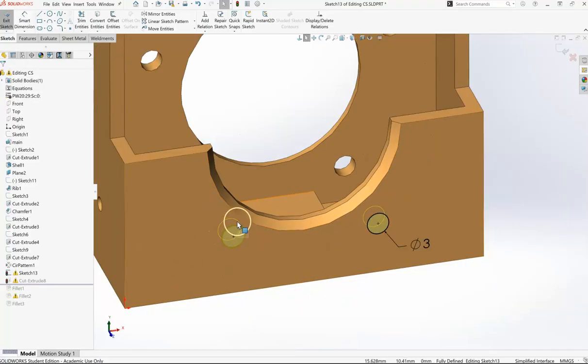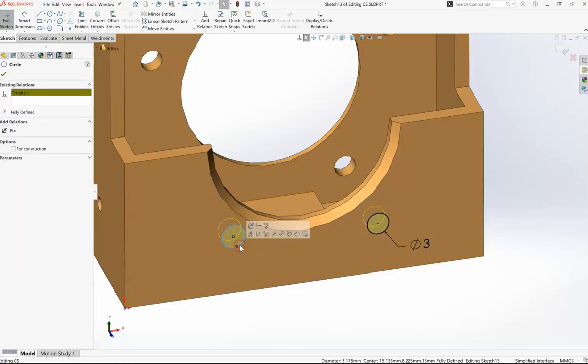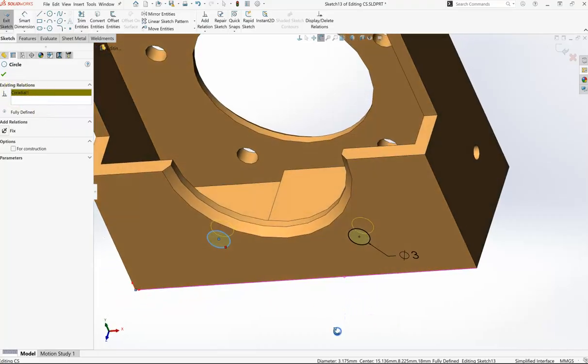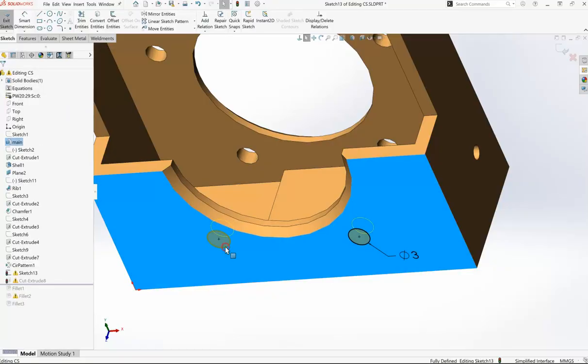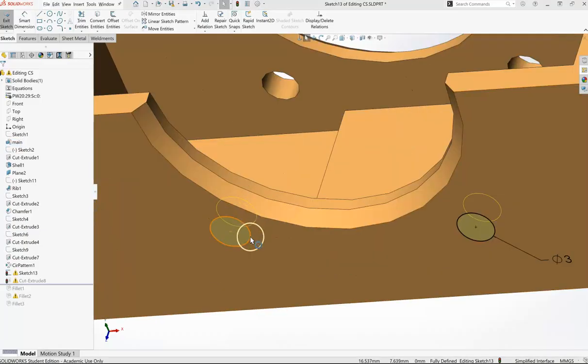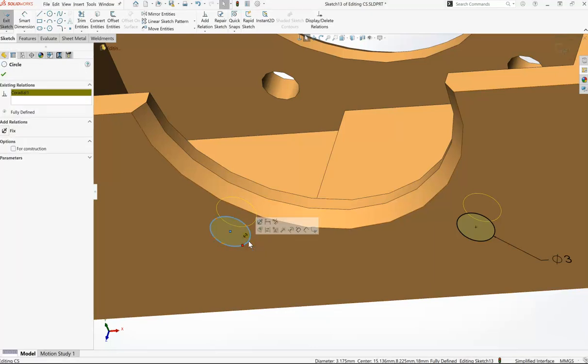And if I click on this circle, it's saying that it's not co-radial. And so we're going to do the same thing. We're going to take this drag handle, so we'll highlight this again, take this drag handle, drag this back to this circle, and right there I want to get that vertical line.